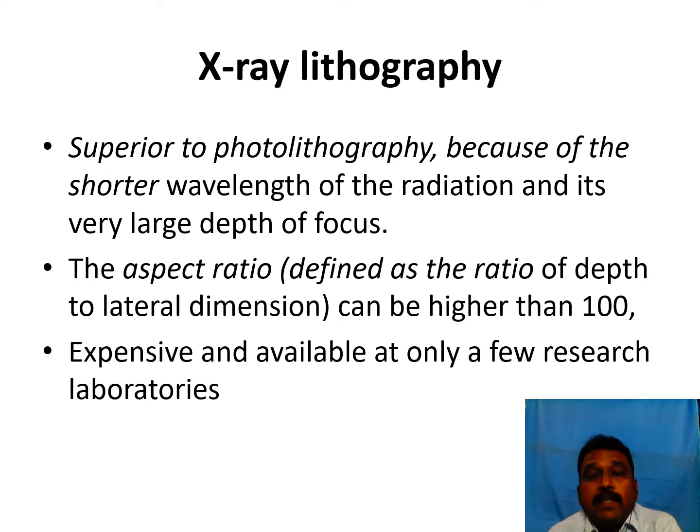And then there is X-ray lithography. It is very superior to photolithography because the wavelength is very short, and there is a large depth of focus, but it is very expensive. So only research laboratories will have the setup of X-ray lithography.